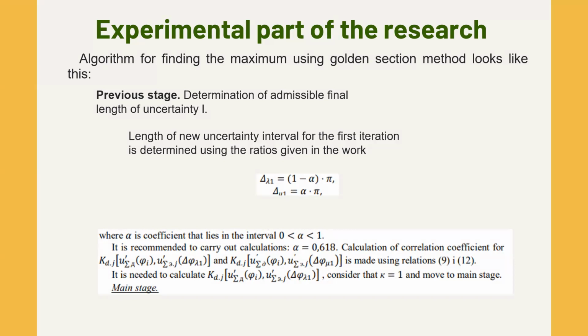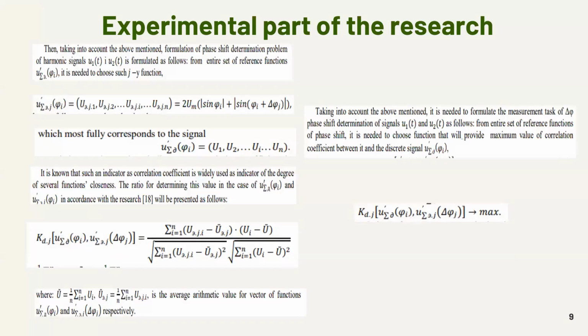After the main operations, auxiliary operations should be applied. After performing amplitude-time analog-digital conversion, it is possible to obtain different kinds of vectors. In order to reduce computational operations and simplify the procedure, it is advisable to switch from time counts to signal phase counts.